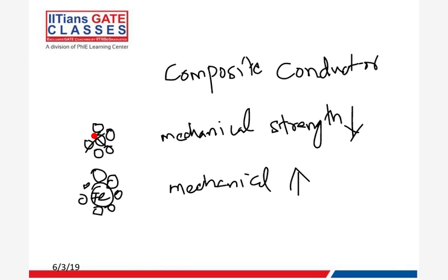There's no issue. So due to the skin effect, the inner aluminum will not be properly used, right? So if you replace that with steel, the effective mechanical strength actually increases. Right?